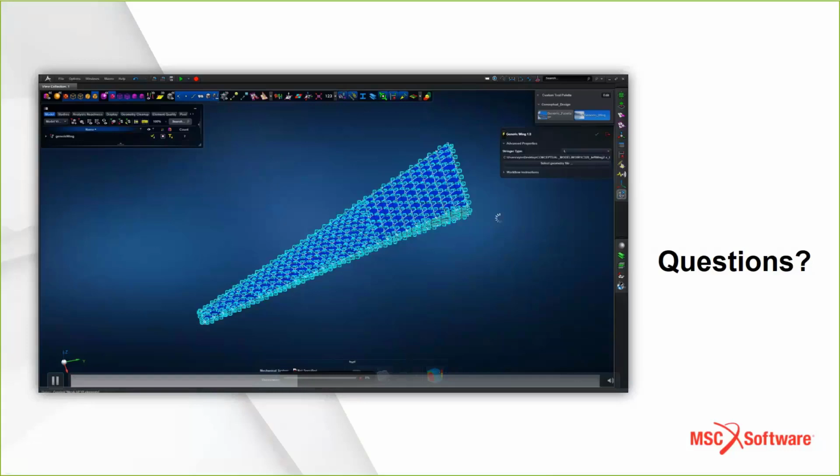Is it possible to give connections between two 3D meshes? Sure, I can do connections between different meshes. I could connect them with perhaps Nastran glue. I could perhaps connect them with RBE2s and RBE3s as well. So I have a lot of options available to connect 3D meshes together.